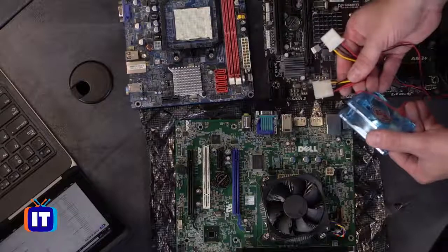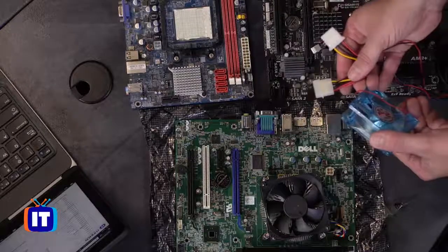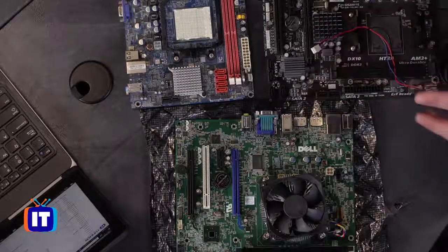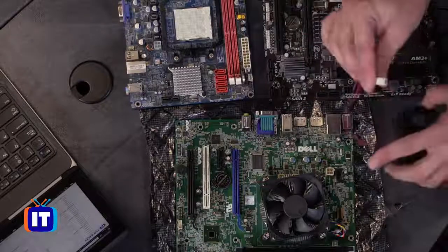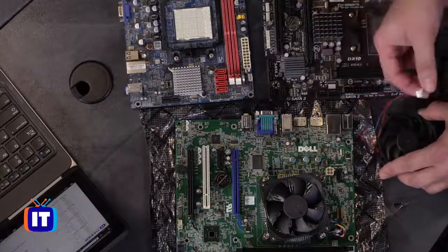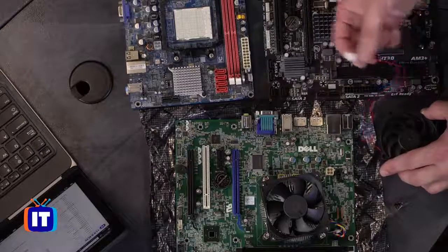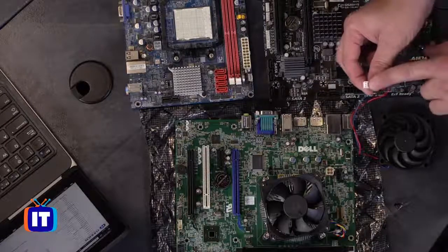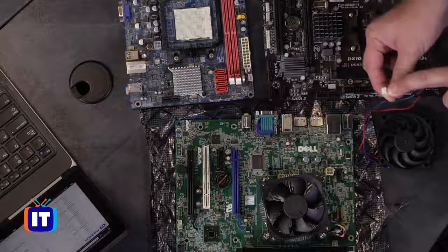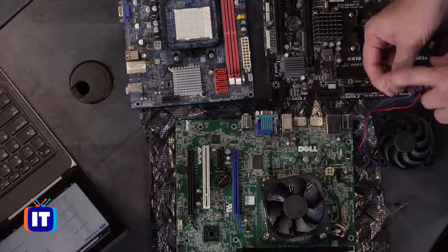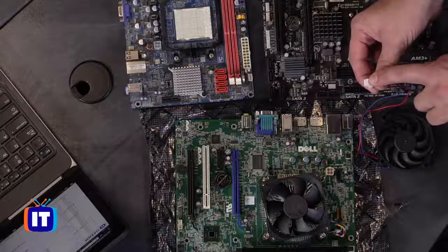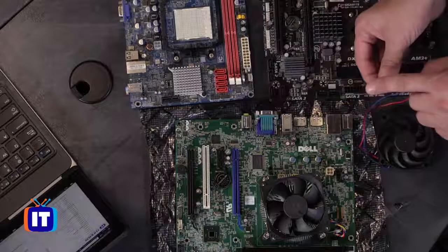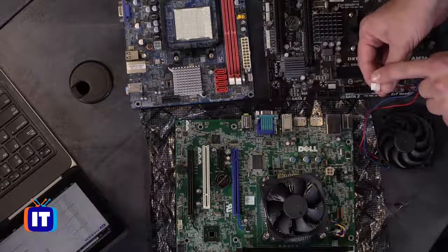A lot of times what you don't get is variable speed, and you don't get some of the monitoring, not diagnostics, I guess more monitoring than anything, that we talked about in our BIOS section. To do that, what you need to have is one of these. They're still a Molex connector, but they got a funny name. It's Molex KK. I don't want you to worry about that. It's just a family, a style of connectors, and they can be all different types, but primarily what you see inside of your computing environment is a 3-pin or a 4-pin. If it's a 3-pin, then it means you can't really monitor it. You'll have your positive, your negative, and then I believe your ground here. If you see a 4-pin, same thing, you got your positive, negative, and ground, but then you have a 4th pin for things like monitoring.